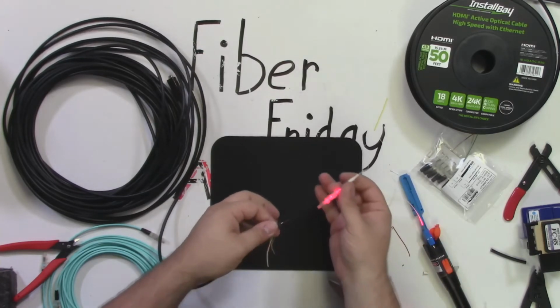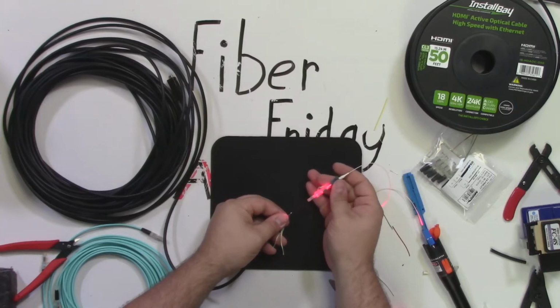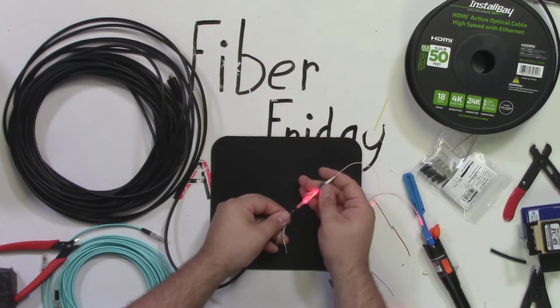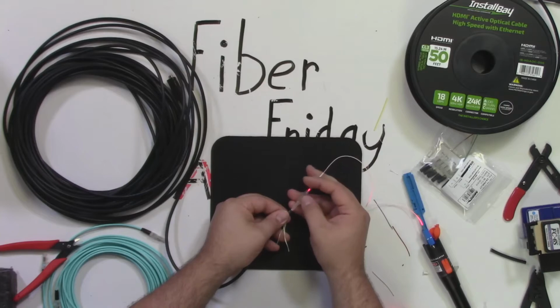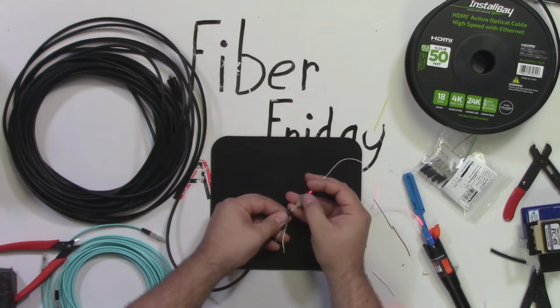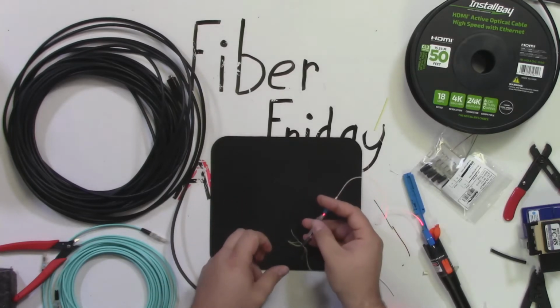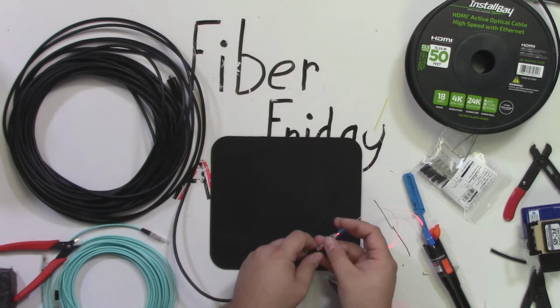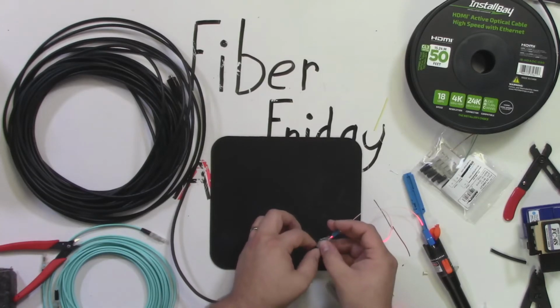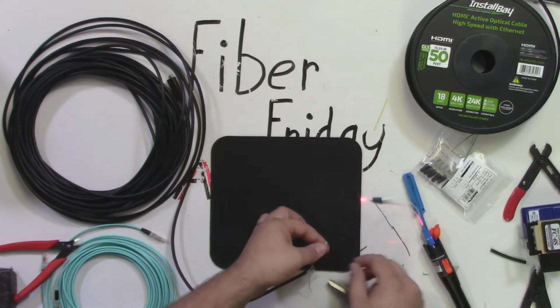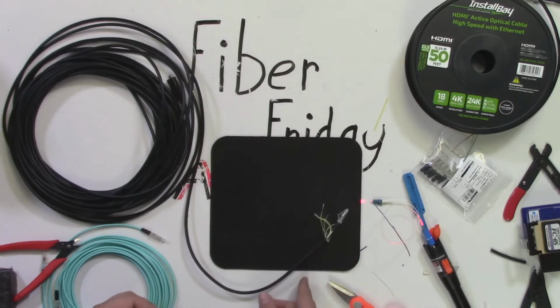Now, I'm going to take the fiber, and I'm going to feed it here inside. And as you watch, the light should dim. See that there? Once that light dims, we're going to come over here and push this metal piece, this metal clip, through. That locks it into place. Once we have that on there, we're going to take our boot, and if we can get everything here to cooperate, make our connection there. Take off the LC adapter there, and we are terminated, and we're done.